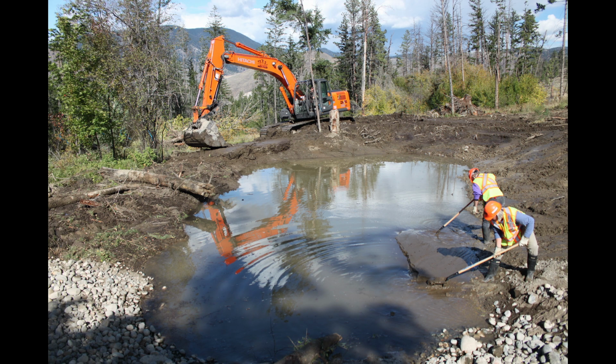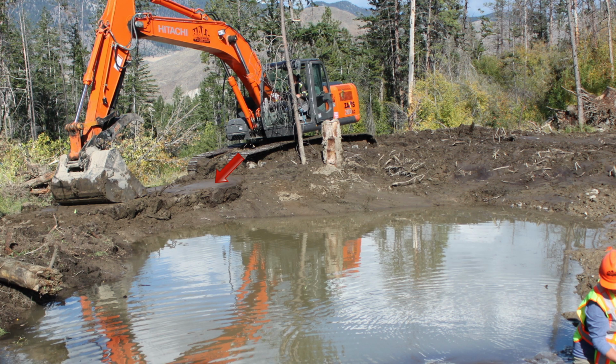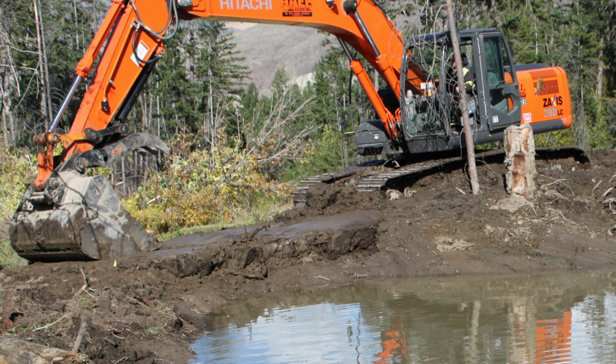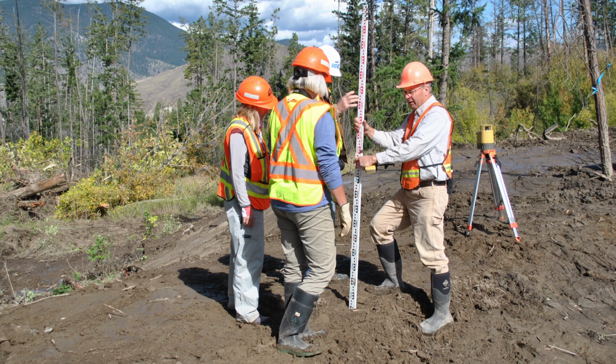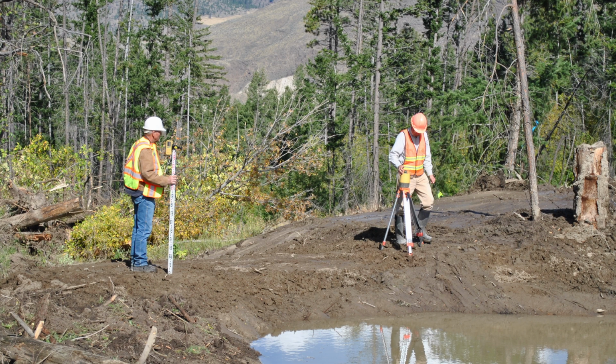Here Tim Hall is rebuilding a groundwater dam that washed out before the rock was delivered. He rebuilt the groundwater dam using loam texture soil because this soil was the least permeable that was available. Tim uses the bucket and the excavator to compact the soil in the groundwater dam. Elevations are taken often with the laser level to make sure that the entrance to the spillway is not too low so it drains the wetland, or it's too high so water does not flow over the spillway. When taking elevations, allow for the thickness of the rock that will later be placed in the spillway.